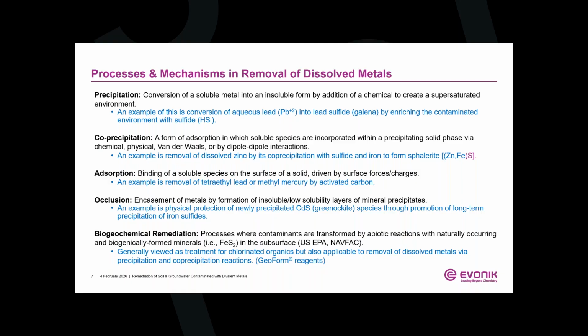Occlusion is something that I'm very big on, and I think is a real strong advantage of the approach we use with these long-lasting reagents. And by occlusion, I mean encasement or encapsulation or locking up of the freshly precipitated metal sulfides by continuously laying down additional layers of either the same metal sulfides or actually profuse precipitation of iron sulfide, which is very low in solubility,